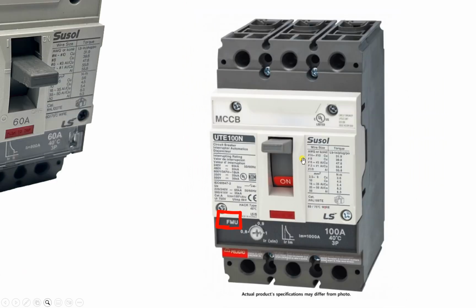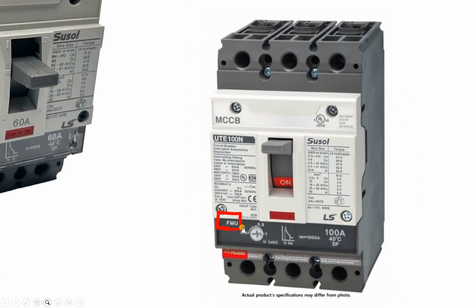Now there is another one called fixed magnetic unit. It means that the magnetic part IM, I can't control it. However, the IR value I can control. As you can see, I can change it to 80%, 90%, or 100% of the given value. For example, if I put it at 80%, it means that the rated current it will start activating at is 80 amperes. If I put it at 90%, it means IR will be 90 amperes. 100% means I'm taking the full value. So this is semi-adjustable. I adjusted the IR value, however, I don't have control on the magnetic. That's why it is called fixed magnetic, because the magnetic itself is fixed.